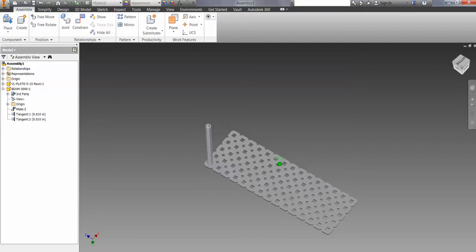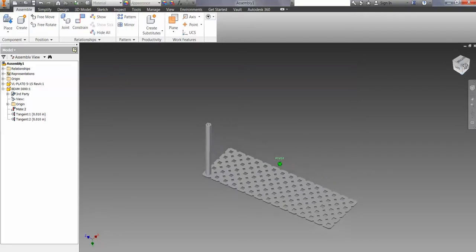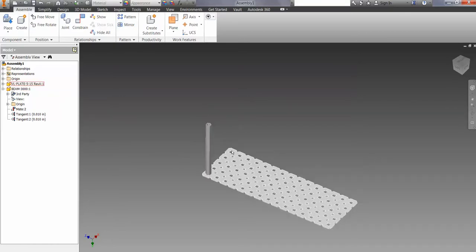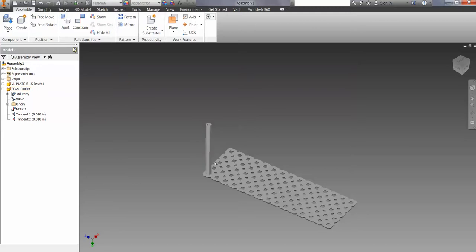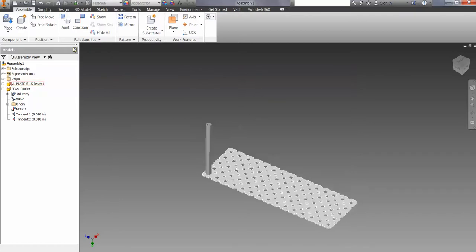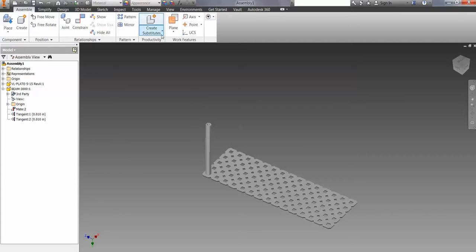It does require some work, but there is a command that's called mirror, and we can mirror what we've done here on another side. And so since this is nice and even here, I want to mirror this side with that side. To do this, I'm going to need to create a plane that I'm going to need to mirror off of, because a mirror requires that flat surface that's being mirrored on. Just like when we look in a mirror, the flat surface of the mirror reflects our image back to us.